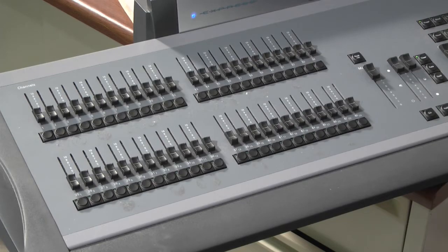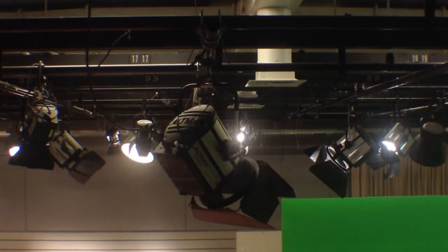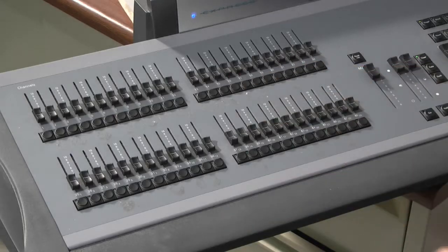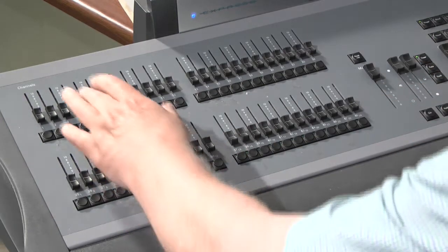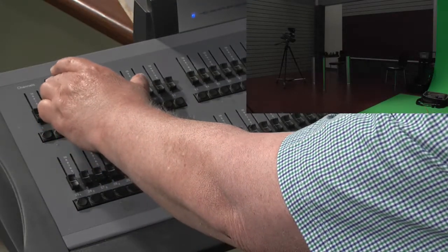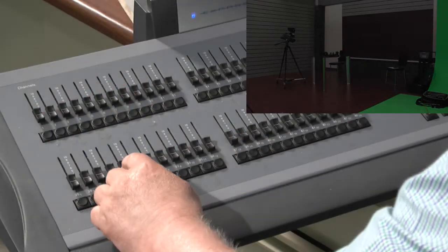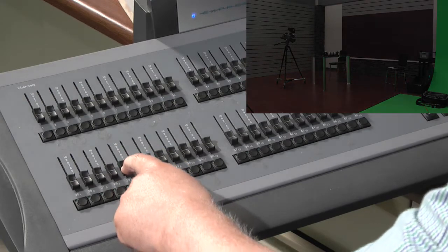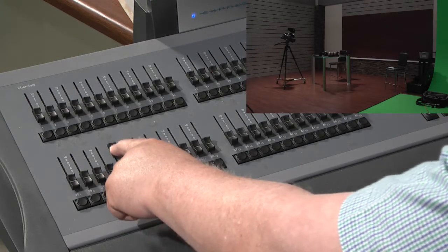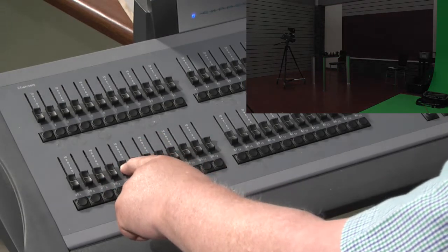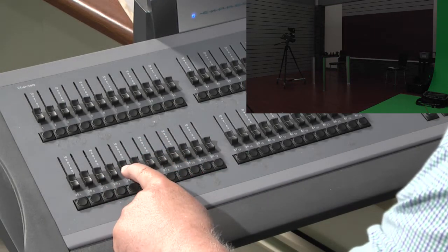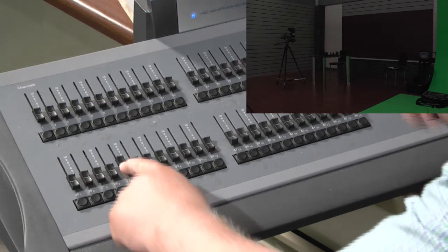The light sockets, or the fixtures, the lights themselves, plug into the numbers. There's a number on the grid that corresponds to the numbers on the channels. These are called channels. To use a channel, what you do is you simply push the slider up to some location. Okay, so here we go. So there we have, I'm pushing the slider up, and as I push the slider up, the intensity goes up from 0. I'm on fixture 29, which is circuit 29, to 100.